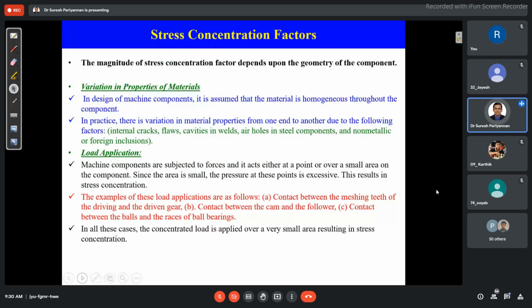Any porosity, blowholes, or composition changes can be easily detected with the help of computed tomography. That is a three-dimensional X-ray. We can see the component's internal structures layer by layer. Any porosity or air bubbles present can be seen in the different images. Based on the images, we can conclude whether the material is good or not, and then modify it later based on our application.